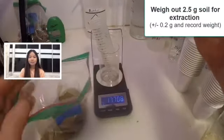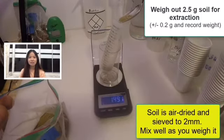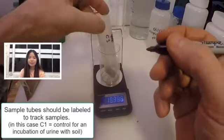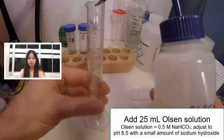The first step of the procedure is to weigh out 2.5 grams of soil for the extraction. The soil is air dried and sieved to 2 millimeters before weighing. 3 samples are prepared and the sample tubes are labeled to track samples. Then, 25 milliliters of extraction solution is added to the soil of the 3 samples.